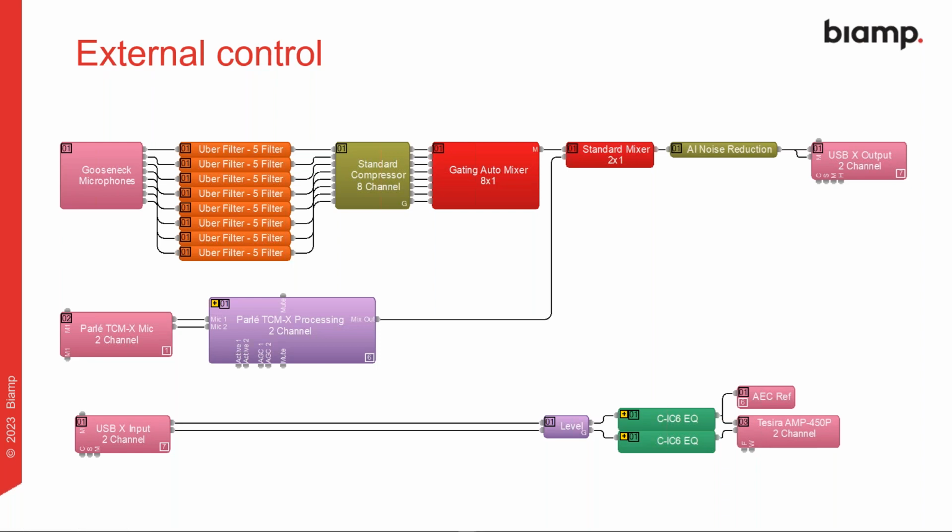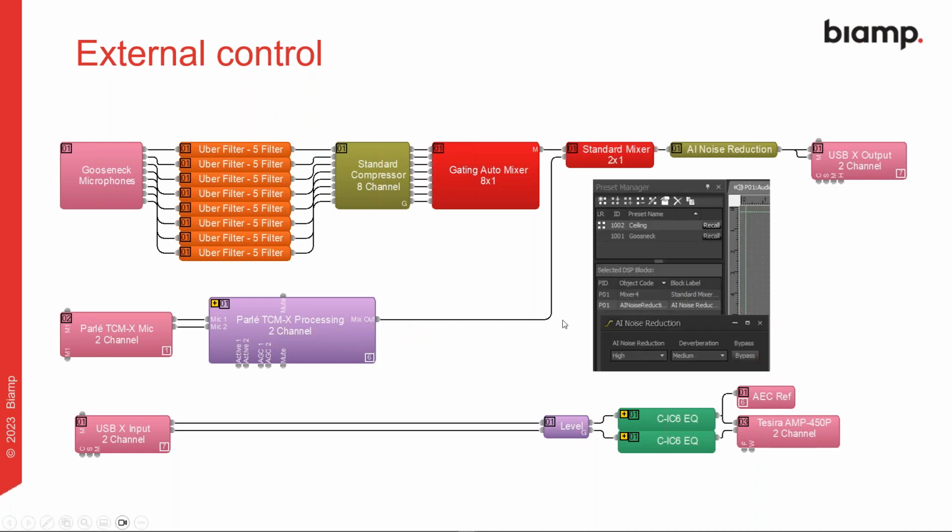It's going to give them a really direct pickup for recording purposes. Now, when they're also using the AI to make sure that they've got a really nice clean signal, when using the ceiling mics, they've obviously got a much different acoustic path than a gooseneck microphone would, simply because of the placement. So you might tune the noise reduction for the gooseneck mics and be happy with it, but then when you switch over to the ceiling microphones, it may not be achieving the desired result.